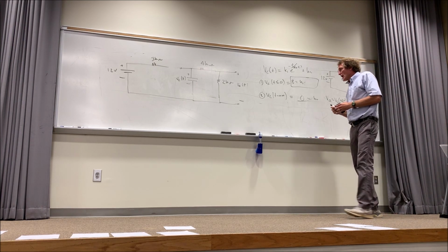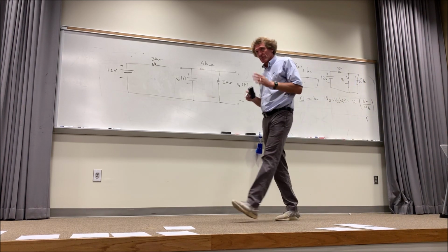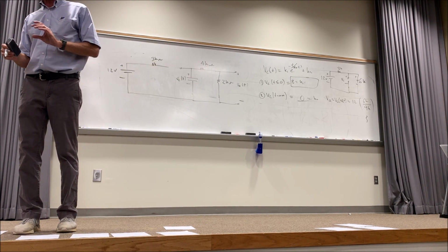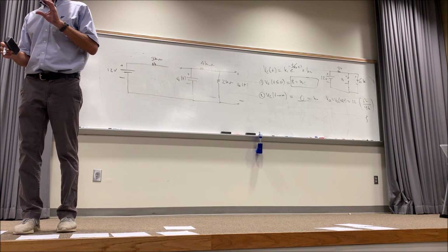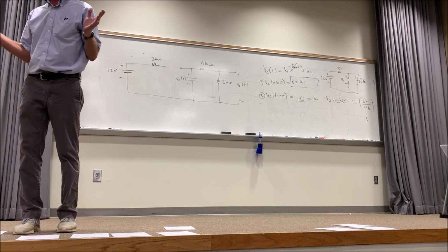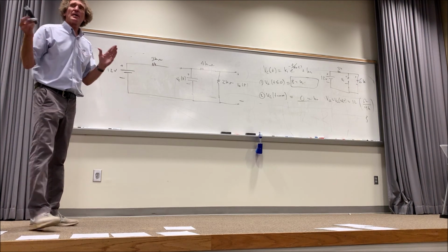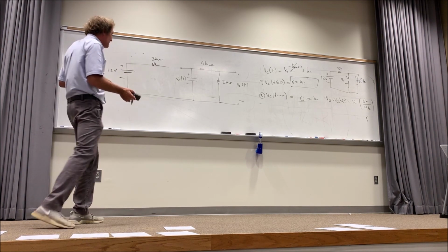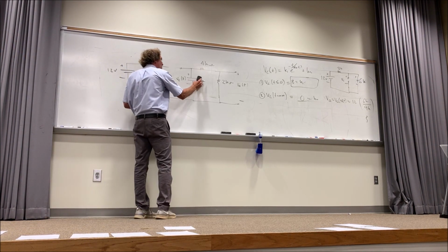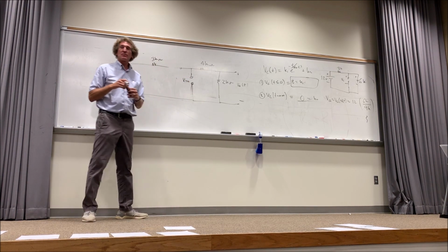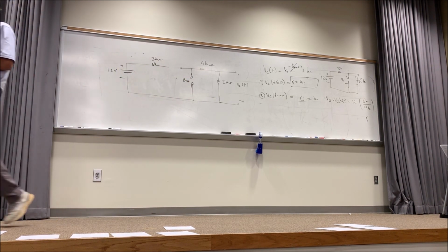Now, I got to get R Thevenin too. Remember, R Thevenin across the capacitor in the region after the switch does its thing, opens or closes, right? So what is R Thevenin? Think about R Thevenin as t goes to infinity. What would it be? Well, R Thevenin, how do I get it? I erase the capacitor. Don't have to erase the capacitor. But in a certain length of time, you're not going to worry about that capacitor. You'll see through this.